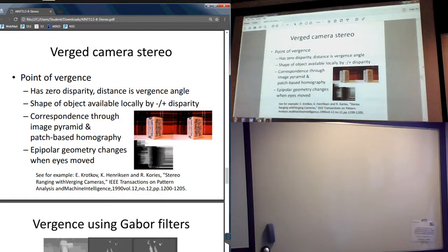The echo that comes back is timed, corrected for the measurement error, and then overlaid on the colour picture as a point cloud of depths. So there's two stereo techniques, but the one we're using is the passive one, which mimics human eyes and mammalian eyes.